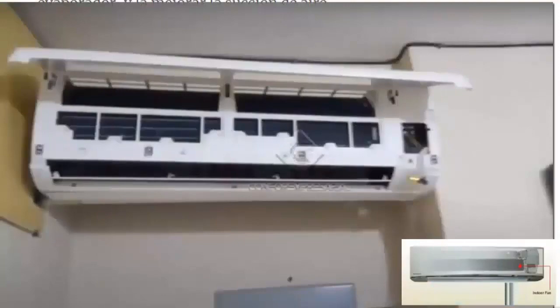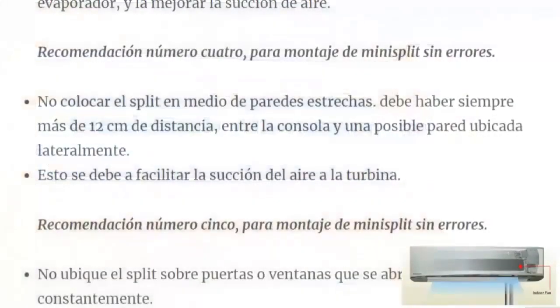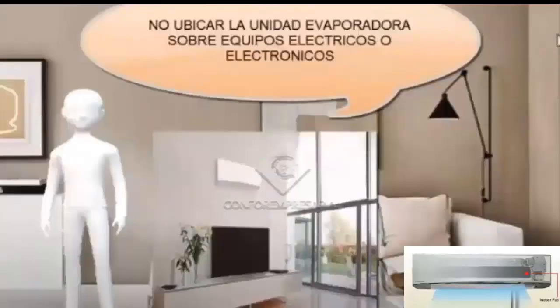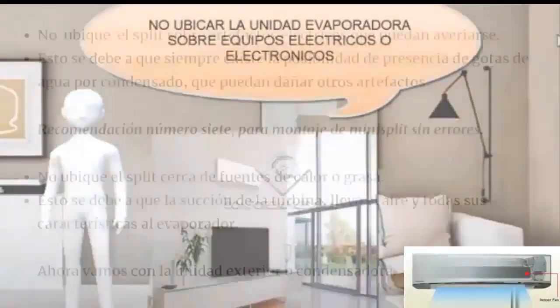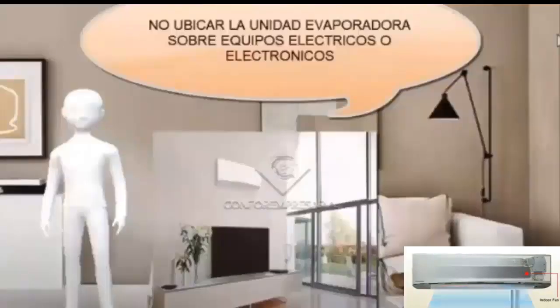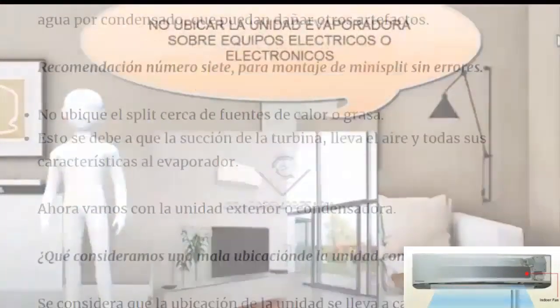D. Remember, keep the indoor unit away from doors, windows, heat sources, and dust. E. Place the indoor unit as high as possible, respecting the distance to the ceiling. F. Do not place the indoor unit on top of appliances.